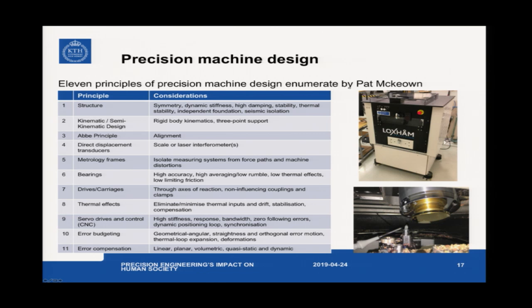As an example, we see here a small precision machine that manufactures highly accurate parts, for instance, mirrors in different applications in optics and so on. To give you an understanding, the tool size here could be around 1 millimeter in diameter. So it's quite small things in this case. Things you need to think about when you design: thermal effects, for instance, how your gradients are, how your control system with the electric motor heats up the machine or the machinery. That needs to be taken into consideration.